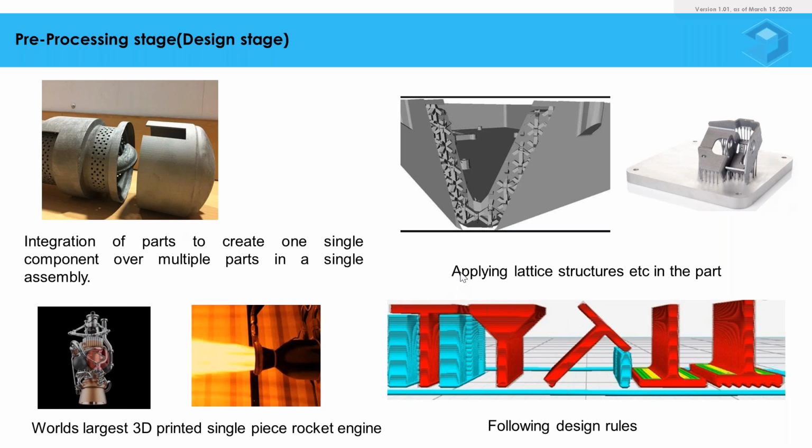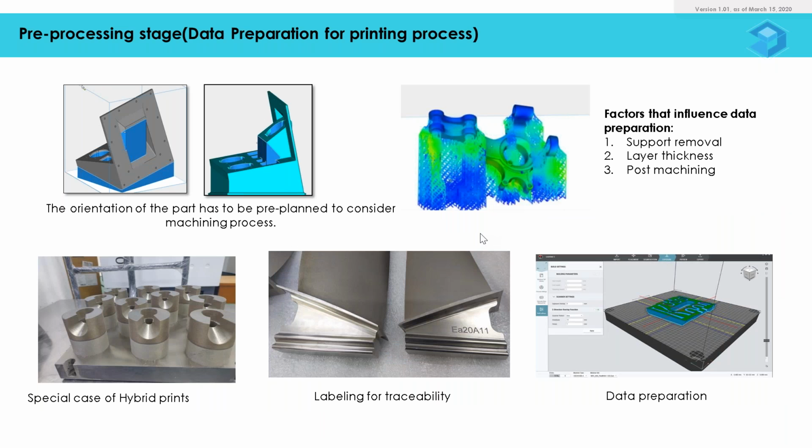So another area is the lattice structures as well. So how can we lightweight with the lattice structure but still have good amount of strength? So this is an example of a pre-processing stage where softwares like Magix help us optimally orient the part, and support structure is a kind of a waste byproduct. So how can we reduce that? That is the thought process over here.